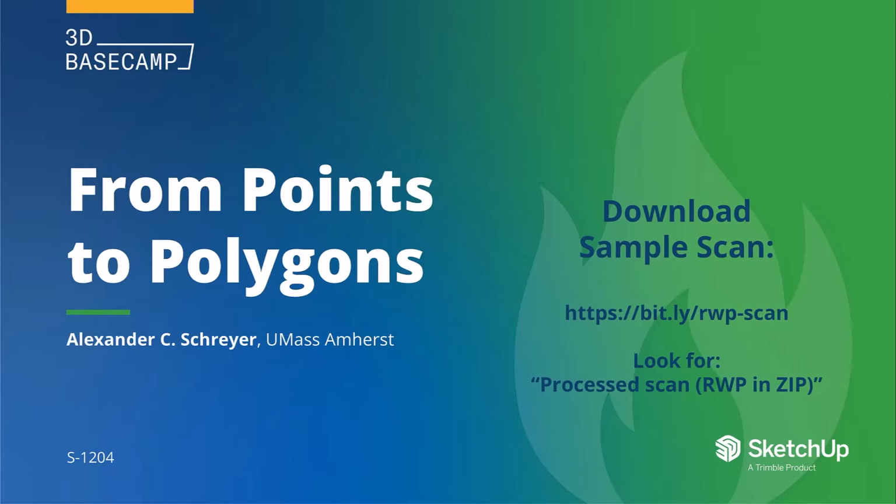But what we're going to do in this presentation is use point clouds to model in SketchUp. Now, in order to work along, if you want to do that, you can download a sample scan that I have prepared for you at the URL that you see on the right there. You want to look for the process scan RWP in zip. It comes as a zip file, and you need to unzip it so that you can use it. You also need access to Trimble's Scan Essentials extension that's on the Extension Warehouse, and you can install that pretty easily from over there if you want to work along.